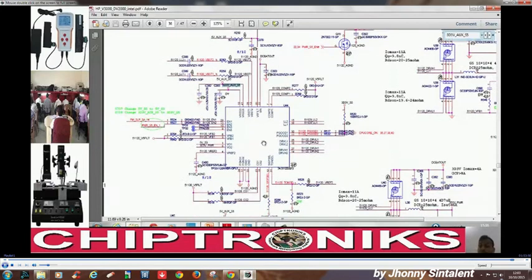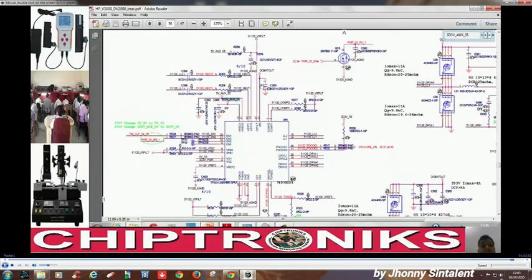What is the input? We had already discussed. Input is V in DC bat out. So now we have to check whether DC bat out is coming or not. We had already discussed in our previous class how this DC bat out and V in is generated, right? So in that case we have to find whether DC bat out is coming or not. If DC bat out is coming and this LDO voltage is not generated, then this IC is faulty, right? Now we will change this IC.